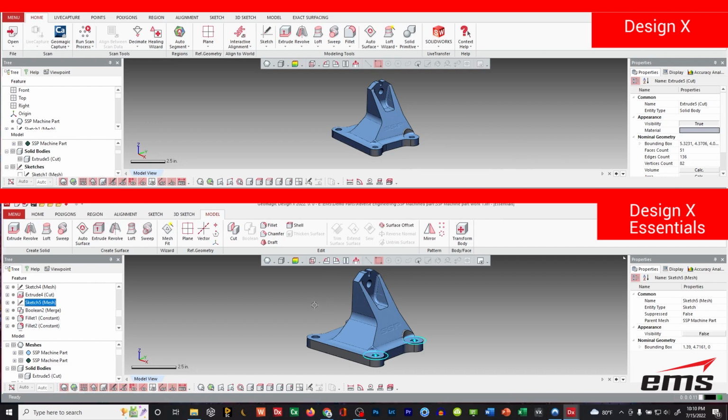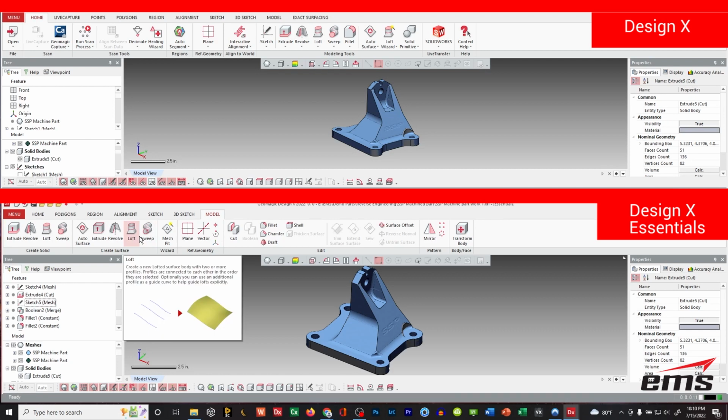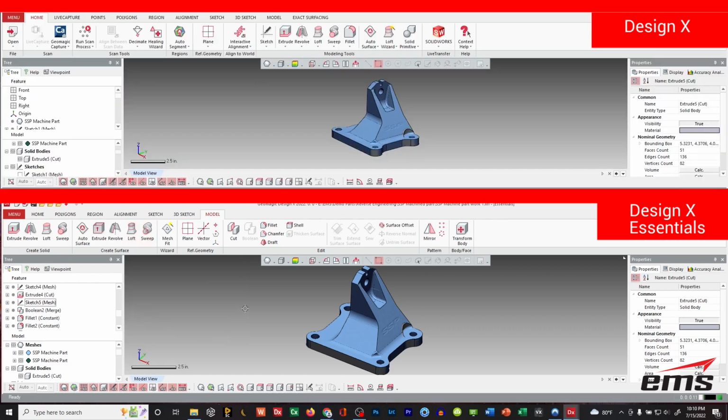If you're doing more mechanical parts like the part you see here, and they could certainly be much more complicated as far as number of features, but generally they're prismatic. You might have a few mesh fit surfaces, some lofts, some sweeps, these kind of basic shapes. You're going to be fine with Design X Essentials. Things may take you a little bit longer to do because you don't have some of the wizards or some of the automation, but you can definitely get the job done with Design X Essentials.